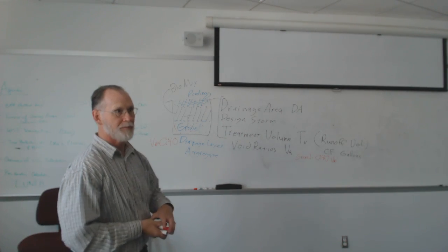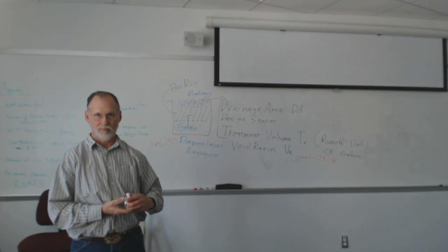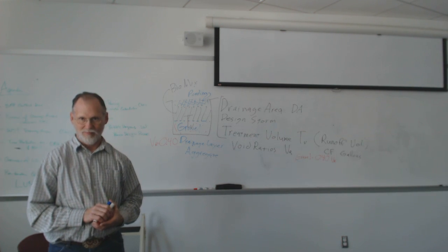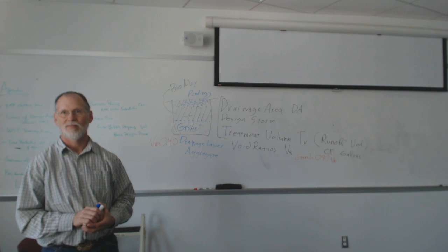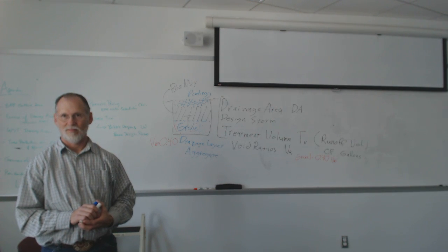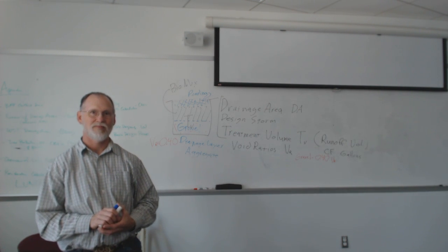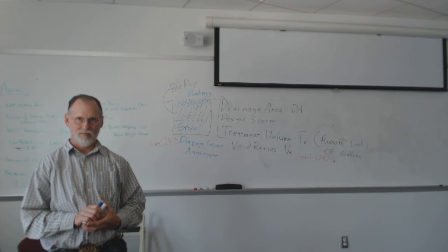Oh, I'm sorry, that's just like a multiplier. So for 1 cubic foot of space, you have a 1 cubic foot container, you fill it with this particular kind of gravel, really only 0.6 cubic feet is gravel, 0.4 cubic feet is pore space that can be filled.